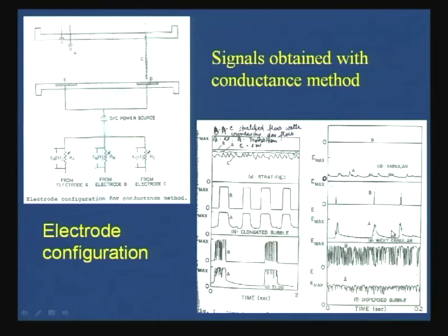So, you can very well differentiate between wavy annular here and annular here, they are definitely different. See the dispersed bubbly situation. Since a large number of bubbles are coming and hitting probe B, we get such a totally undulating signal. This signal is somewhat similar to the signal we obtain in the liquid slug for the slug flow pattern, which shows that the liquid slug is aerated and resembles the dispersed bubbly distribution under those circumstances.